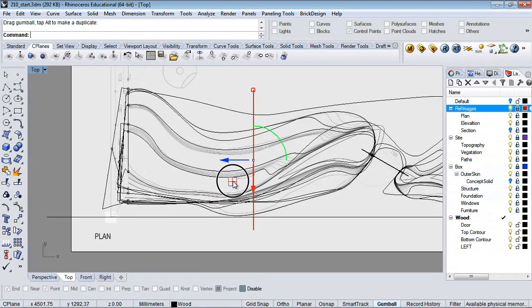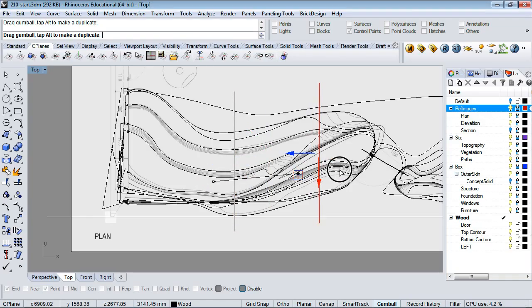move this and I can describe this curve, but one thing that sometimes is helpful when you're doing these sweeps on rails is to think about tangency. So here it's okay, this is kind of perpendicular. But if I go over here, like on this, oops. So you see this line here where it starts to drop back.